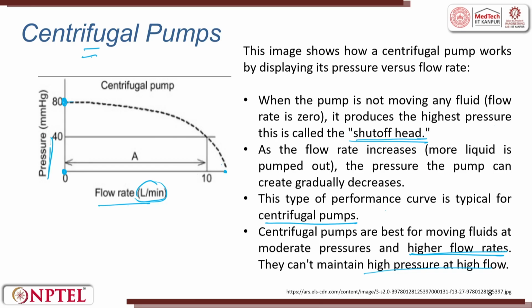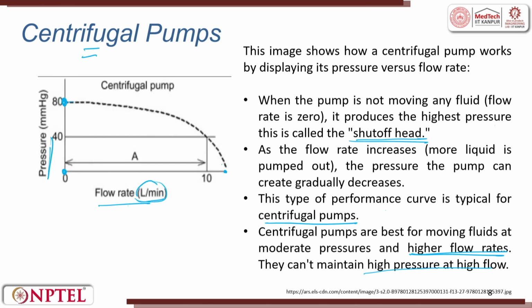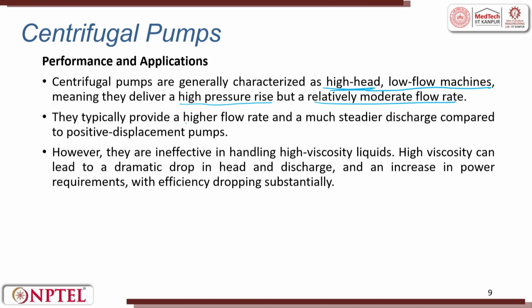So, it increases the flow rate, the pressure decreases. So, the performance and application, if you see for centrifugal pumps, are generally characterized as high head, low flow machines, meaning they deliver high pressure rise, but relatively at a moderate flow rate. The same thing what they have displayed here. They typically provide a high flow rate and a much steadier discharge compared to positive displacement pumps.